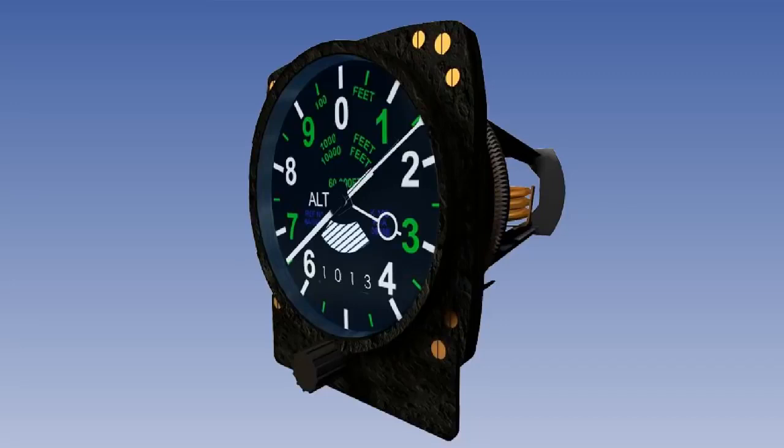In this lesson, we are going to look at the principle of operation of the pressure altimeter and how the pressure altimeter is calibrated. We will also look at the simple altimeter, the sensitive altimeter, and the servo-assisted altimeter. The pressure altimeter can be thought of as a pressure gauge, which senses change in static air pressure and, by means of calibration, expresses the change of static air pressure as a change in altitude.